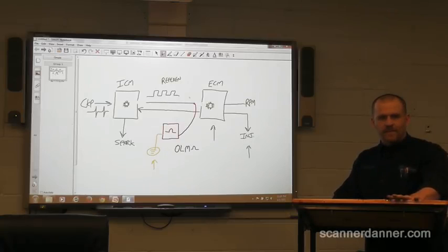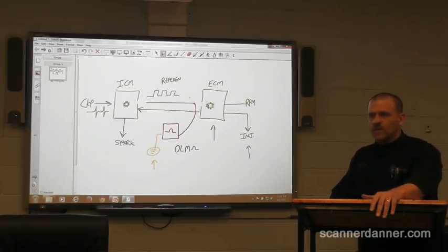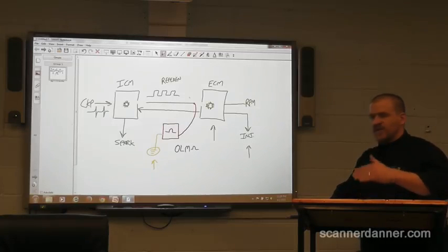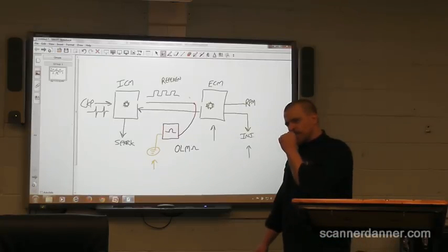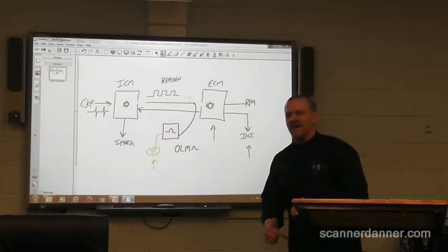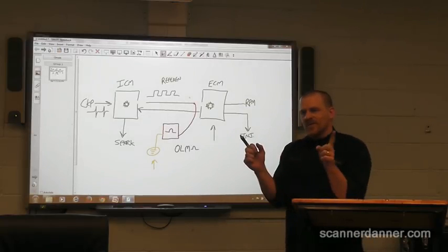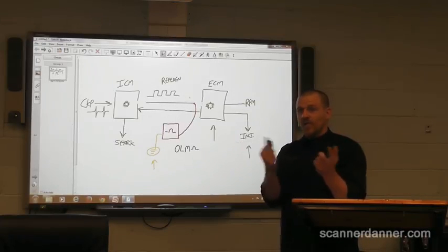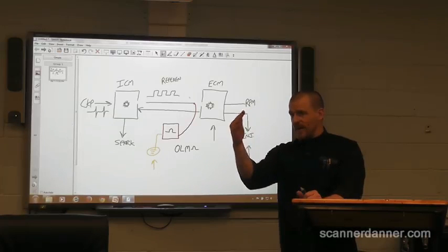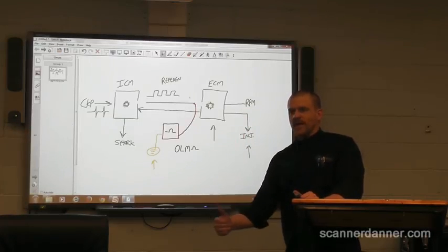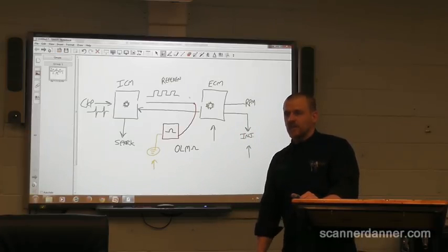Questions on that? It'll move itself all the way up to the highest scale. In fact, as soon as you turn your ohm meter on, it'll always be on the highest scale, because the leads aren't connected to anything and there's nowhere for them to go. So as soon as you turn your auto ranging meter on, it'll be on the mega ohm scale, and it'll work its way down as that number is changing.